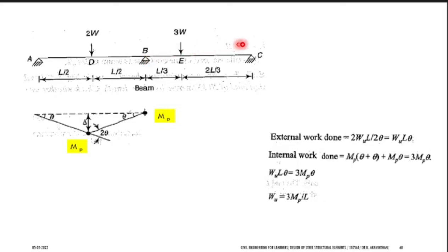If you have any other support after this, it will prevent the lifting. For the previous case, do you have any other support apart from that? See, this was your span, and if this span tries to lift, this support will not allow it. You have a hinge here, this will not allow it to lift, it will drag down. Whereas in the previous case, if you check the diagram, you do not have any hinge or supporting point.